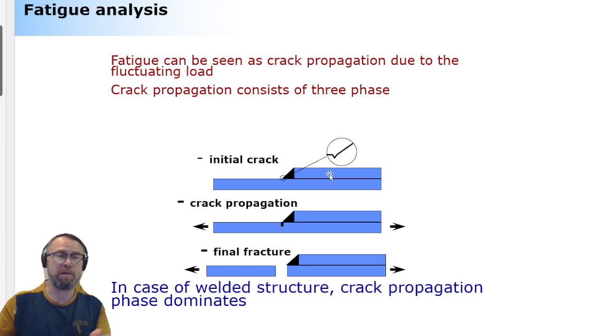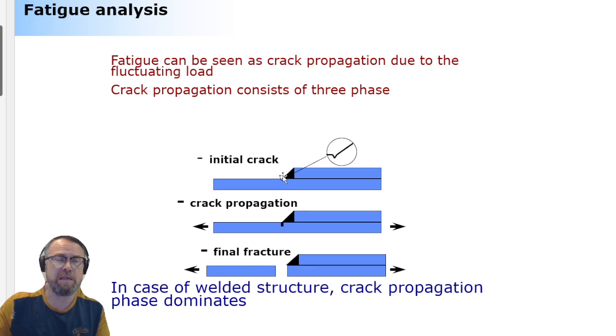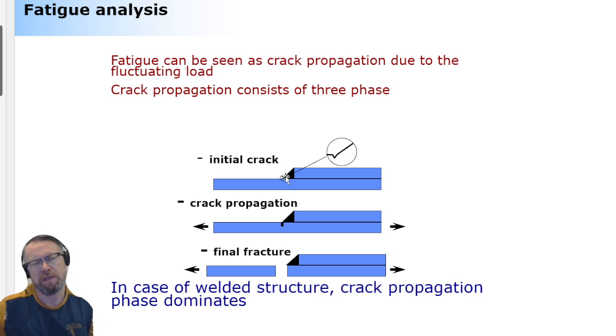And that's a big problem because in machine components like the crankshaft, the components you can find in your car engines, their fatigue life mainly consists of initial crack propagation, I mean, how the initial crack grows. Whereas in welded structures it's already there, and it's hard to get rid of. There are post-processing techniques that help, like you can go and heat the weld toe by TIG welding. You can use hammering to get rid of this, but all of them are cumbersome and not easy to use. Crack propagation, that's when the crack is growing. That takes most of the lifetime.